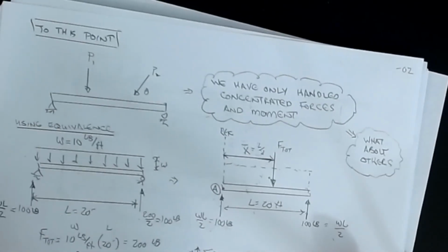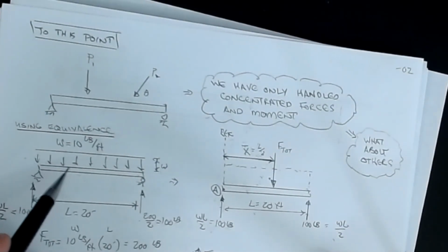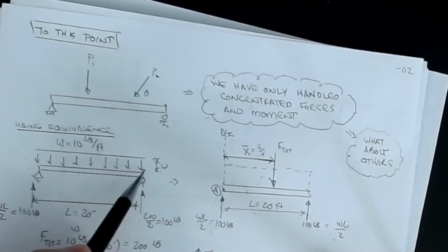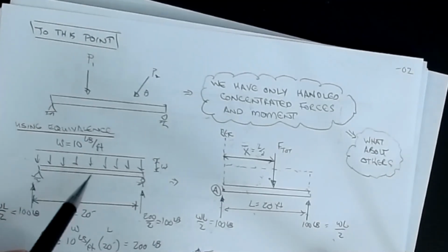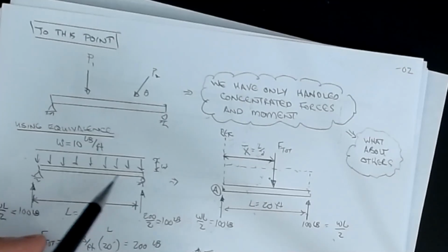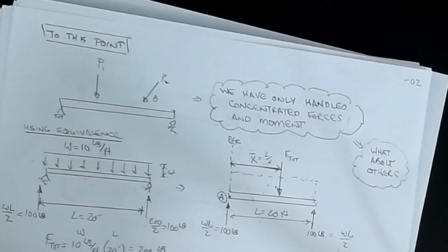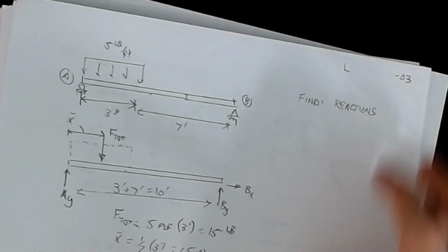So really what it boils down to is that the centroids of forces are very similar to centers of area. This is kind of a rectangular load, right? Well, the center of a rectangular load is in the middle, L over 2 from each side. It's the same idea, except now we're doing the exact same approach for forces. So let's try a little bit more complex one.